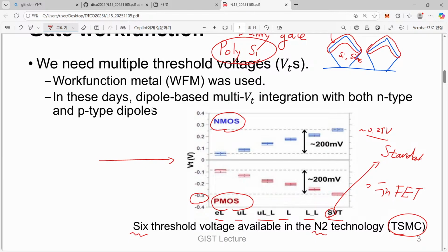There is an estimation about threshold voltage. When you have VDD, then the nominal way to get the desirable value for our logic technology is just to take 1/3 of this VDD. So this is the typical number. Please think about our VDD. In this case, what is our typical value for VDD?